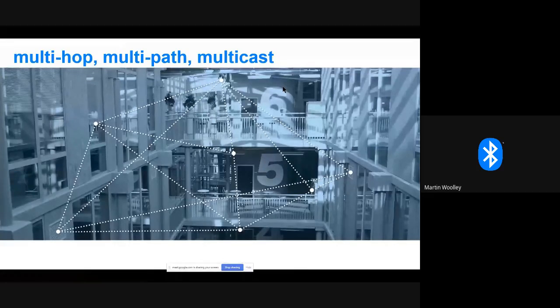So that's multi-hop delivery. Now, the way hopping works, just to be clear about this, the devices in a Bluetooth mesh network will be all sorts of different types of products. So in a smart building example, there'll be lots of lights that are mesh nodes. There'll be switches, dimmer controls, thermostats, air conditioning units, and sensors, light sensors for example, and occupancy sensors that tell you if somebody's in a room or not. And whatever the product type, there are 4 special roles from a networking point of view that any node can, in theory, take on, because they're all implemented in software and they're all enabled or disabled through configuration.